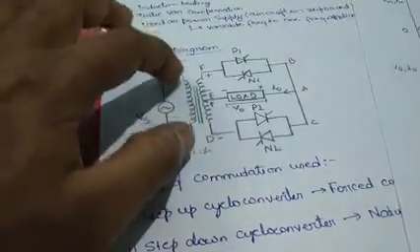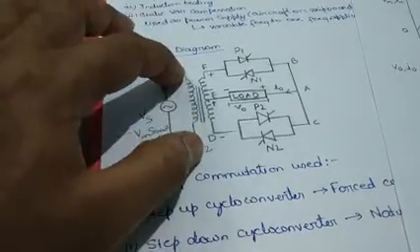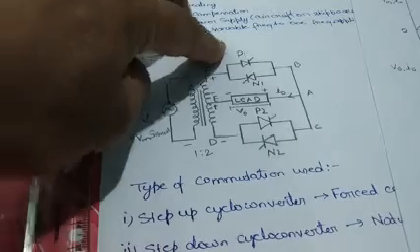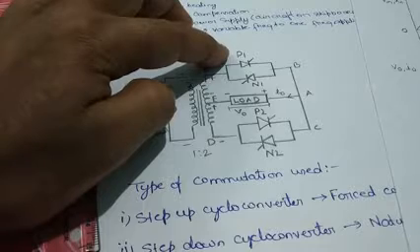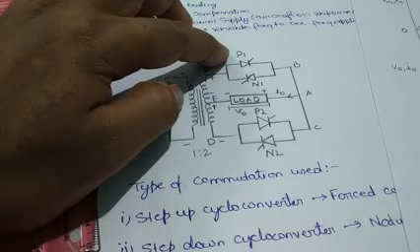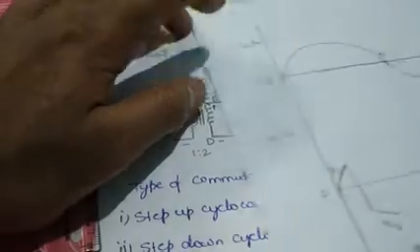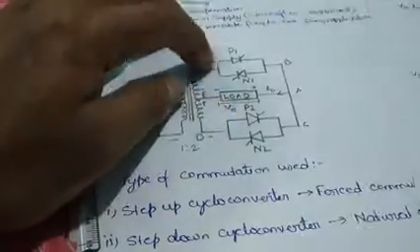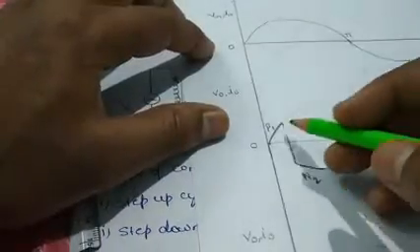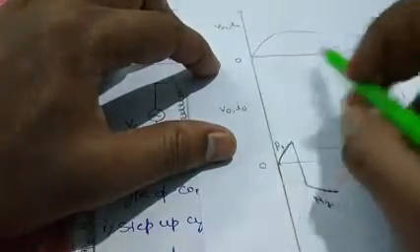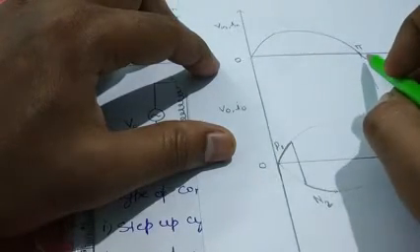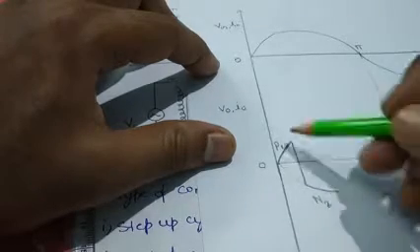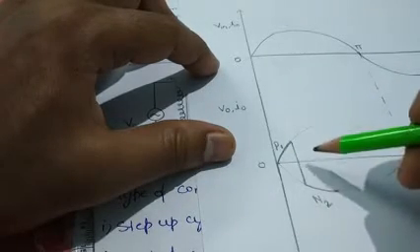The input is still in the first half cycle, and in that duration we have turned off the P1 thyristor one time and again triggered P1 for the second time. Now this can happen because we all know that the thyristor has a turn on and turn off time in the range of microseconds. We have discussed this earlier in the switching characteristic. For a 50 Hz cycle, this half cycle time is 1/100 seconds, which is a very large time. So in that case it can switch on and switch off a number of times.